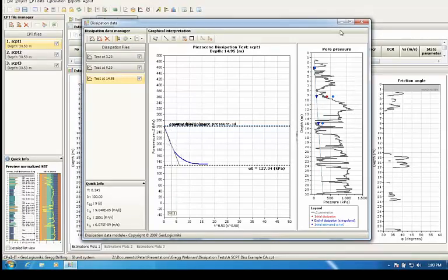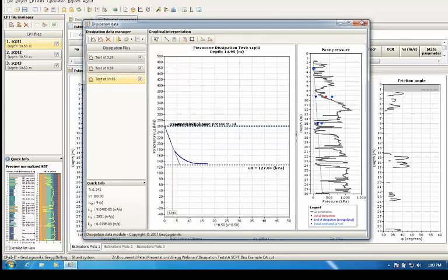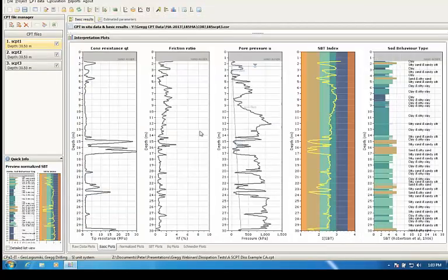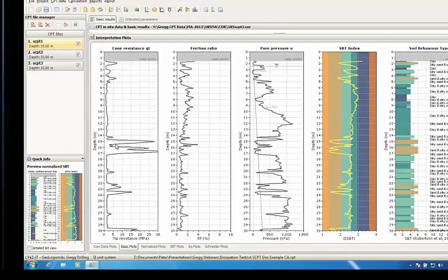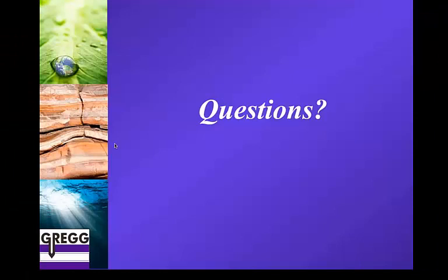So here's this one that's in the sandier material. The log time, very, very difficult to interpret. So let's just switch the axis, then go back to here. Now it's on the square root time. So that more complicated one now doesn't look so complicated on square root time. And very quickly line up the initial portion, ask it to calculate, and there's the T50. You can see it's 9 seconds. So it's basically saying, well, that's well below 60 seconds, so there's a strong likelihood that this was partially drained.